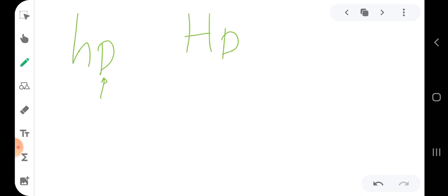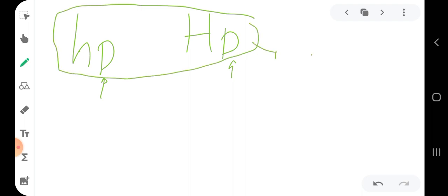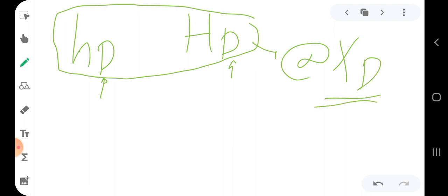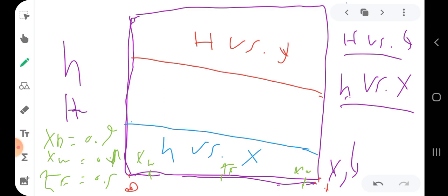D represents the distillate. So this is the enthalpy at the distillate. So both numbers will be determined at XD, because they represent the distillate. So you will search here, we locate our XD here, see, it is here. So you are going to draw a vertical line, okay? So this will be your H capital D, and this will be your H small d.